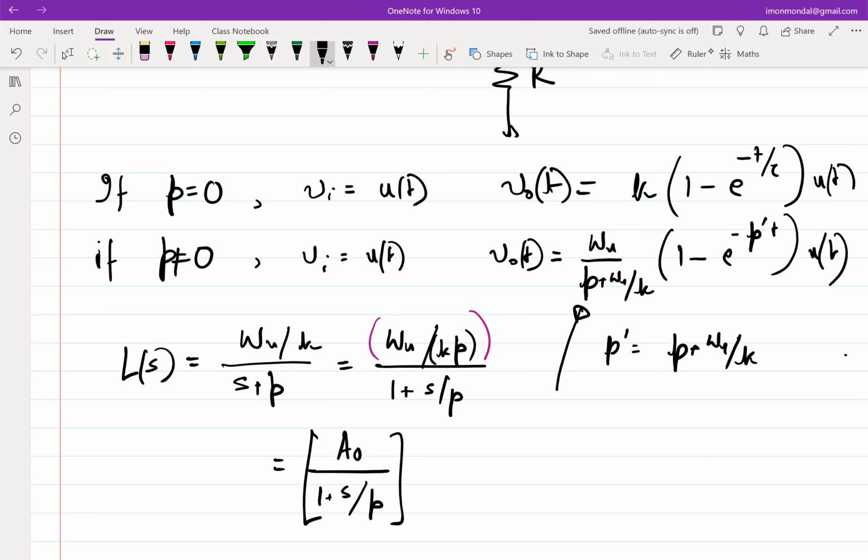So you have to design your integrator. It will be a non-ideal integrator because you will not get an ideal integrator. This is our model. So the non-idealities of the integrator should not degrade your integrator loop gain by more than 1 million. That's what it means. So that's where these top level specifications help you to narrow down into what you are supposed to design.